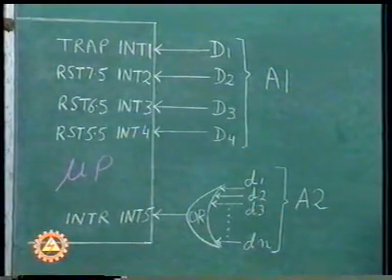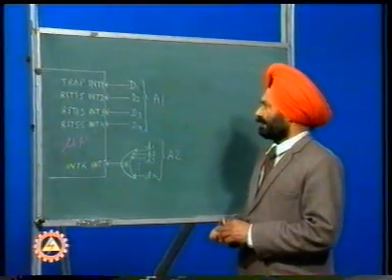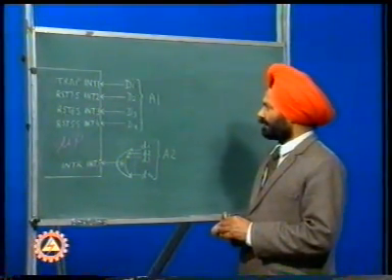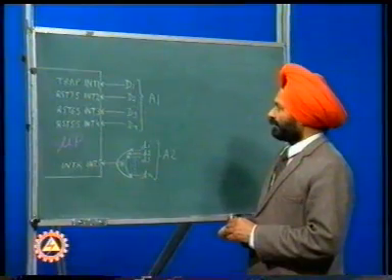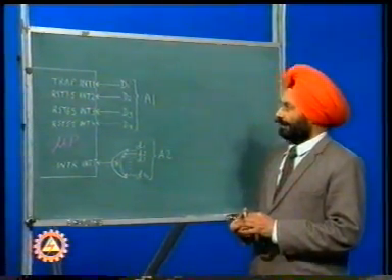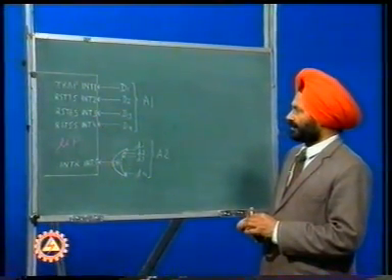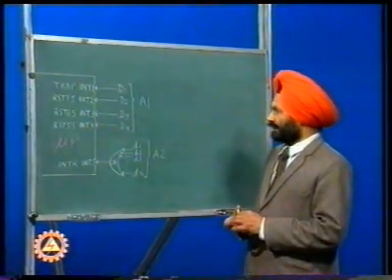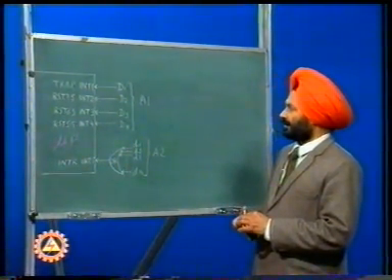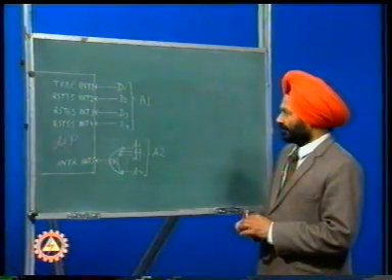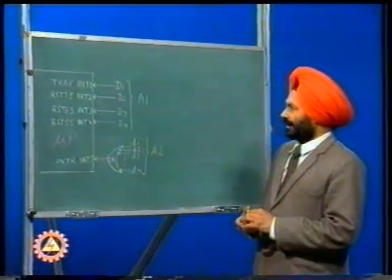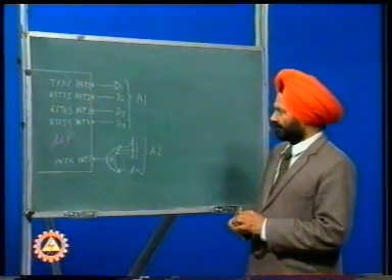On receiving the requests from the interrupting devices, the microprocessor identifies the device according to the priorities of the interrupts. Once it identifies the interrupt to be serviced, it automatically generates the address vector of the interrupt service routine corresponding to the interrupt, which is already placed at a known location of the memory, and starts servicing it. No additional extra hardware is required for this purpose.